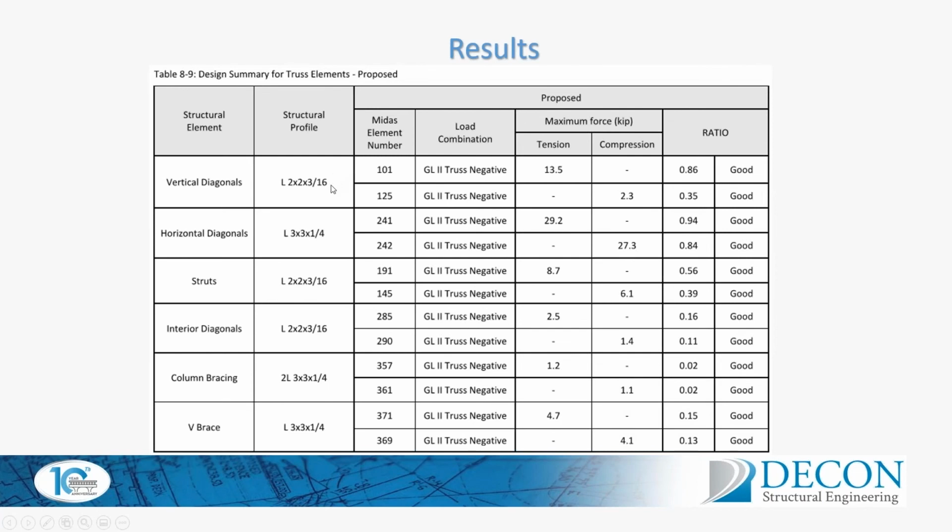The same goes for the truss elements as well. It gives you the profile, for each profile what is the MIDAS element which is critical, for which load case it is critical, and whether it's in tension or compression, and what is the ratio after the design.